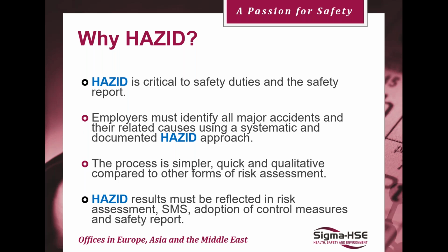And HAZID is good for this because it's simple, it's relatively quick, and it works on an order of magnitude basis rather than going to the far end of identifying all the numbers. You can do it as an order of magnitude type approach, so it's more qualitative. And that means that it's less resource intensive, and it's suitable for personnel at all levels in the organization. So whether it be managers, engineers, operators, or purchasing, everybody can get involved in this sort of thing. And it's a very good learning exercise as well. You learn a great deal about your plant, so it's useful for training.